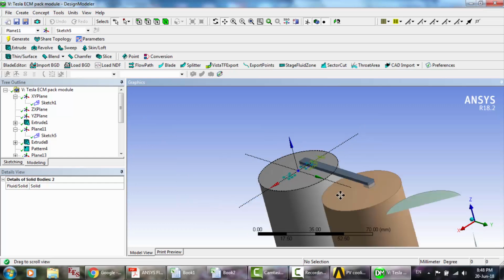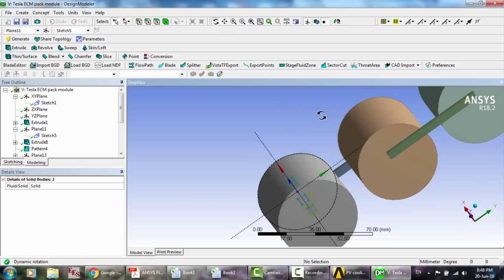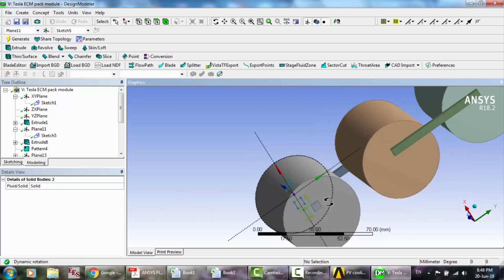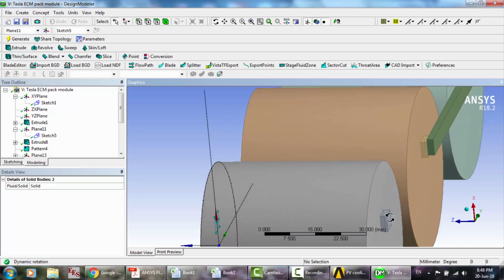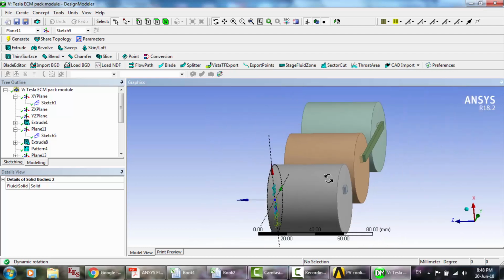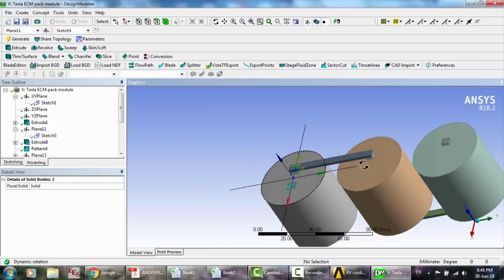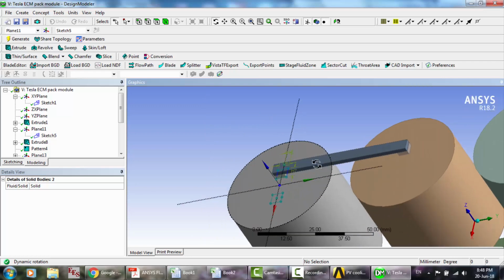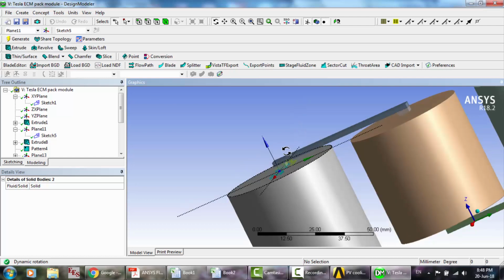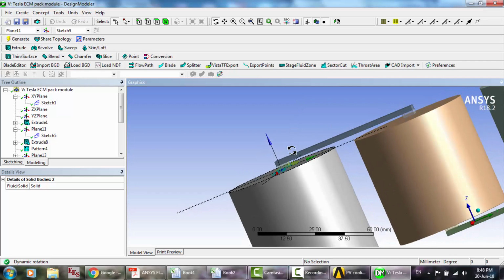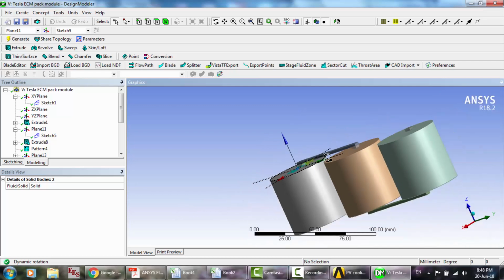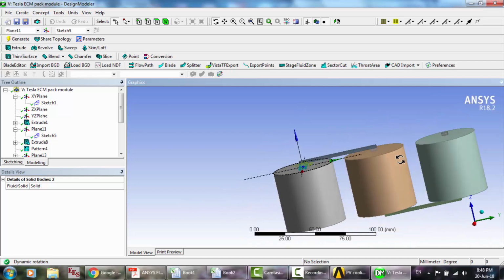Then we make the bus bar, and we have here also the other tab. If this is positive, the second is the negative, using just the pattern technique, the linear pattern. Then this is the bus bar. You can create the bus bar here, or attach or import it.